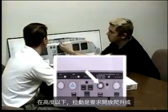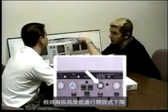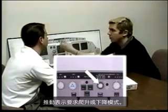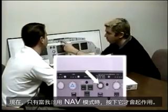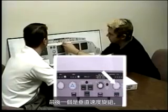Under the altitude, pulling is asking for an open climb or open descent, depending on whether the altitude's higher or lower than what my current altitude is. Pushing is asking for climb or descent mode. Now pushing it only will work if I've got nav mode engaged. And then the last one is the vertical speed knob.